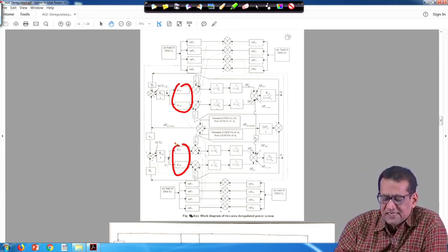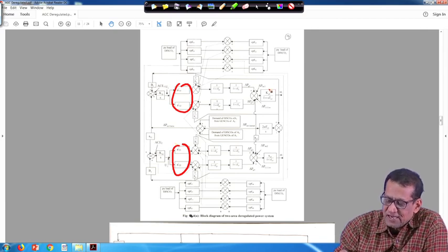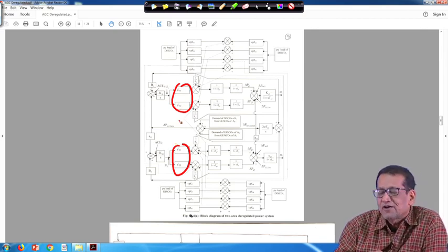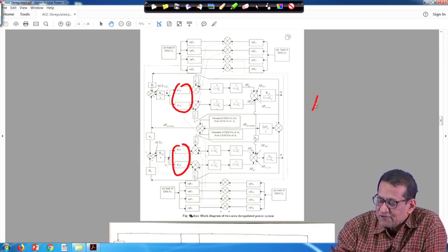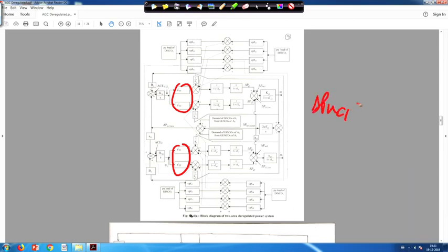But at steady state their effect will not be there when the uncontracted power demand delta PUC1 and delta PUC2 are zero. Uncontracted power demand means that distribution companies have some contracted power with different generation companies, but if all of a sudden a distribution company wants extra power which was not in the contract, that is called uncontracted power demand.